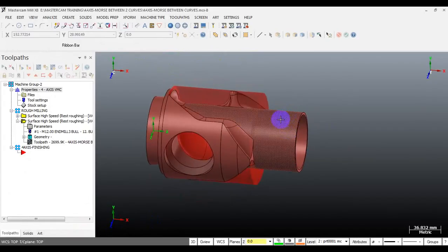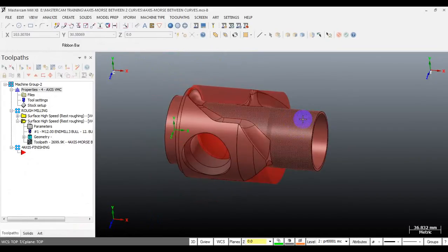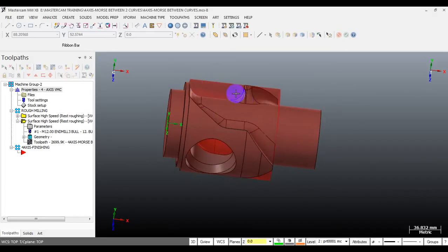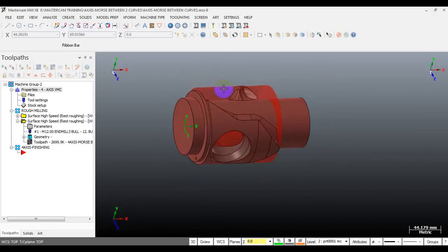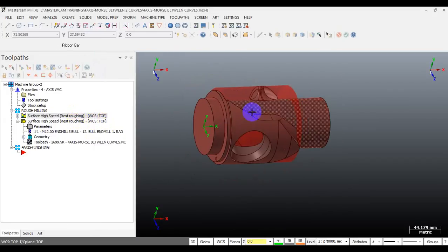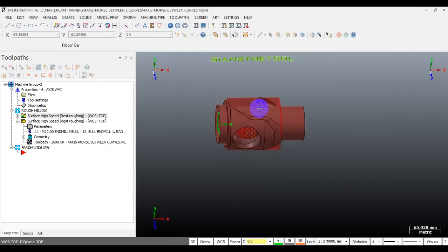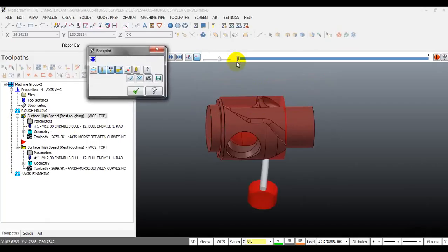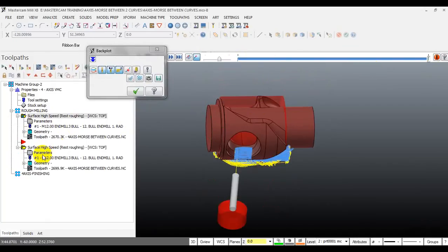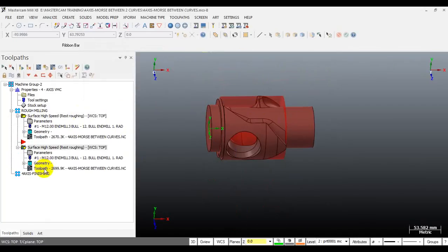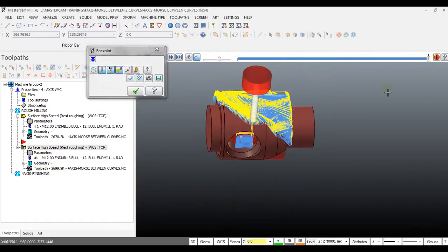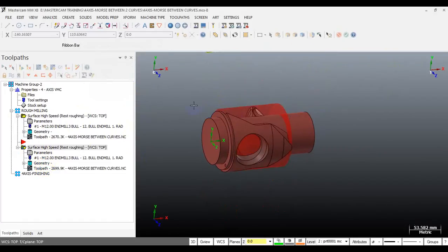and this cylinder area is already machined, and we will machine this area. To save our time, I've just created two tool paths here. These are roughing and rest roughing tool paths to remove the material on this area. So you can review the tool path now. Two tool paths to remove the material before we do the finish cutting.